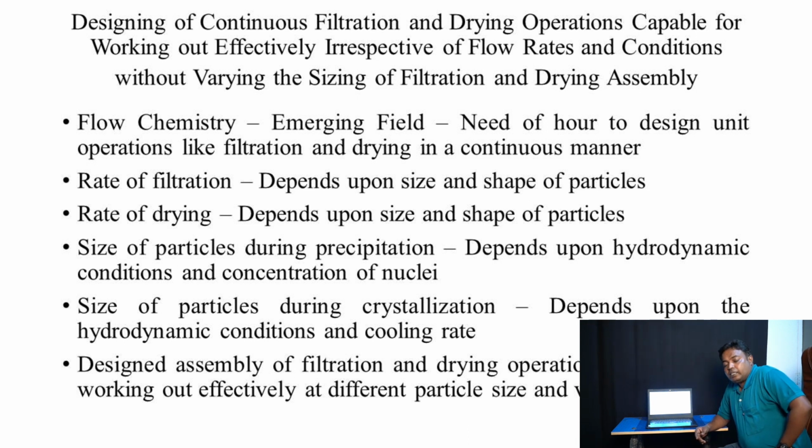But in reverse, if the particle size decreases, then the voidage between the particles decreases and the cake becomes more compact. Therefore, filter cake resistance increases and the filtration rate goes down. And if the particle size decreases, the voidage between the particles decreases, and therefore moisture releasing from the bulk solid meets more resistance and the drying rate is reduced.